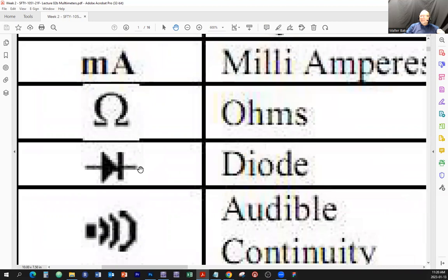So quite often, or almost always, the voltage that is being provided on the leads when you're testing the diode might not be enough to accommodate the needs of certain type of diodes, like, for example, light emitting diodes. So you're going to have a much smaller value than the value that is being specified as the forward bias voltage of the diode.